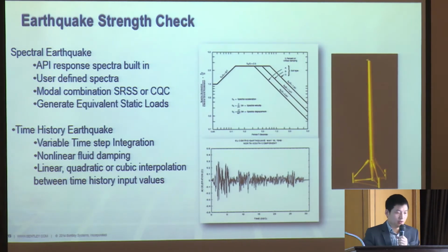Sometimes we need to consider the earthquake strength design. We support spectral earthquake and time history in SACS. For the spectral earthquake, we have the API response spectrum built into the program.